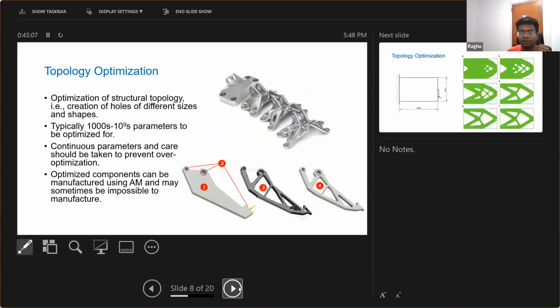Now topology optimization, as I said, has the most flexibility. It puts holes and distributes the holes at different parts of the structure and optimizes for their shapes. Suppose you have an initial solution, this is a bracket again holding two different parts using bolts here. Say you want it to be lightweight again without compromising structural integrity. Now you are using topology optimization to optimize it to the extreme to make it as lightweight as possible. So say this initial solution is 1 kilogram. You don't want the final optimum solution to be less than 3/4 of a kilogram.